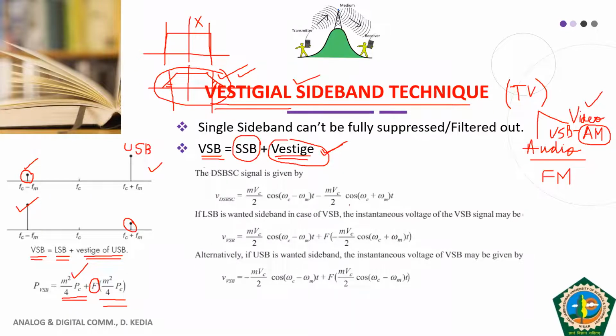Mathematically, this is the expression for double sideband suppressed carrier. Now in case of VSB, this is the complete lower sideband, and this is the fraction of the upper sideband. And if you take it the other way around, this is your upper sideband, USB. In this, we have the complete upper sideband plus the fraction of the lower sideband. So this is your vestigial sideband. I hope this is clear.